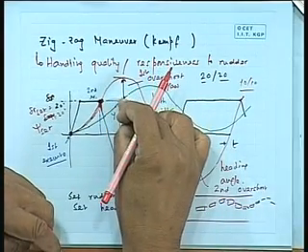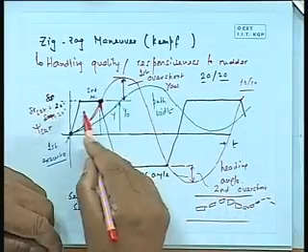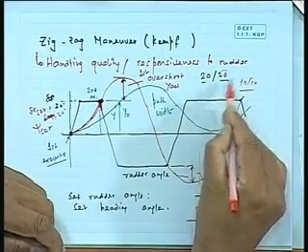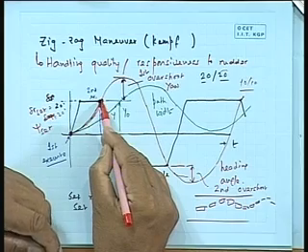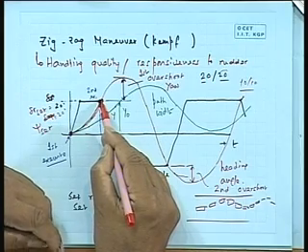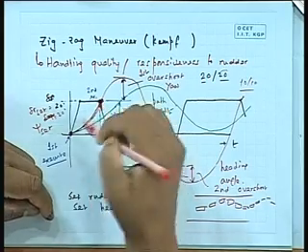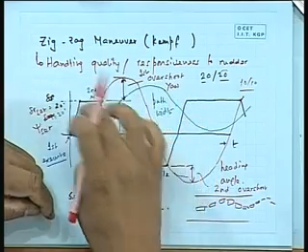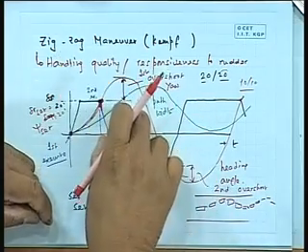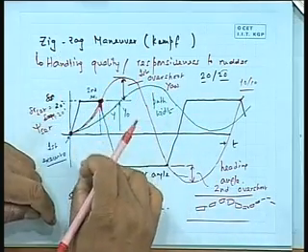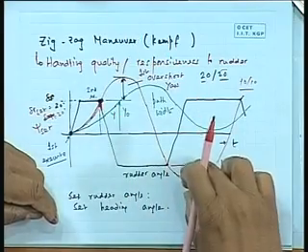Obviously, I have given the rudder angle 20 degree, and my set angle is 20 degree. As soon as my heading has reached that set angle, at that time I have actually swung the rudder back. So it should have come back and immediately started to change, but it did not. It started changing in the same direction for some more time and then came back. How much more angle it turned is my overshoot yaw angle, for the first execute, second one, like that.